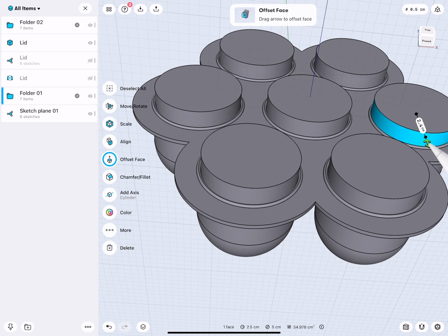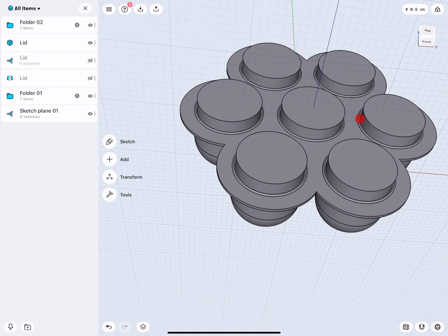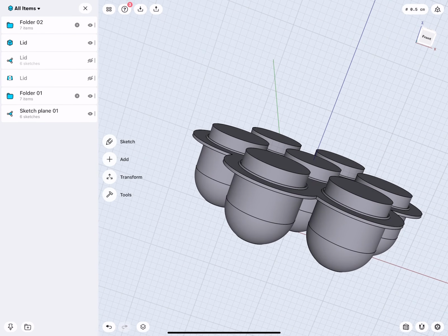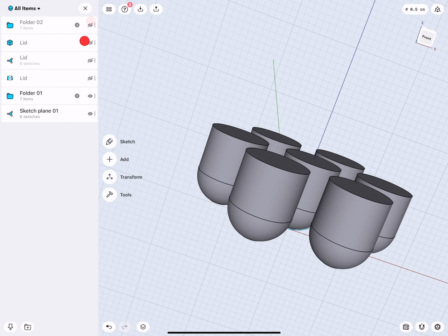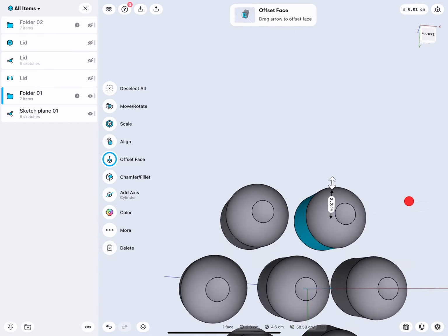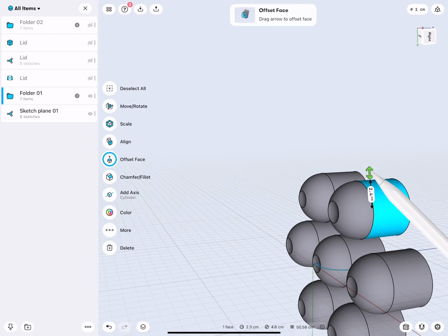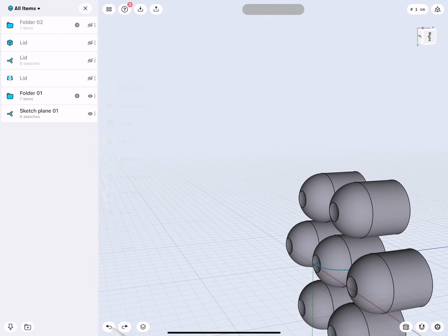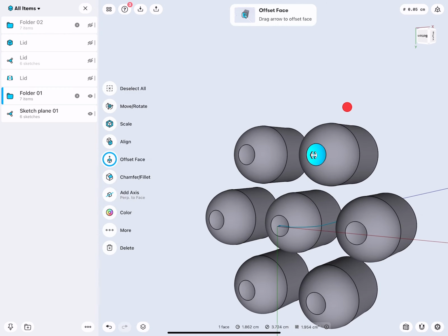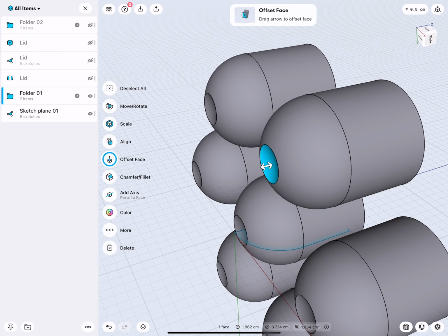And one more. Okay, there. So you see, it's perfectly in. Nearly, there's one detail to show. When I select this face and move it, everything, as you can see, adjusts, just not this one. So here we have to also do an offset change by minus 0.2.